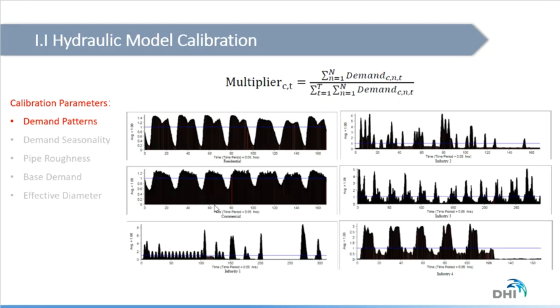These figures show how demand patterns vary with different categories. The residential and commercial demand patterns basically follow a weekly routine with similar daily variations. Industrial user 1 is better described by a 13-day pattern, and industrial user 3 is better described by a 12-day pattern. Industrial 2 and 4 have a weekly pattern, but the daily demand pattern is much different from one day to another.